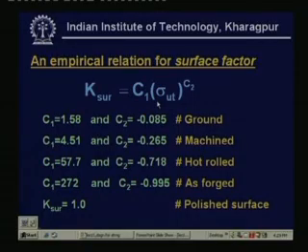So, this shows the effect of surface finish on the value of the endurance limit, and this shows one important factor: whenever someone is going to design a machine element for a fatigue condition, one has to keep track of all the situations which might change the values of endurance limit, thus affecting the design for the number of cycles in actual practice.